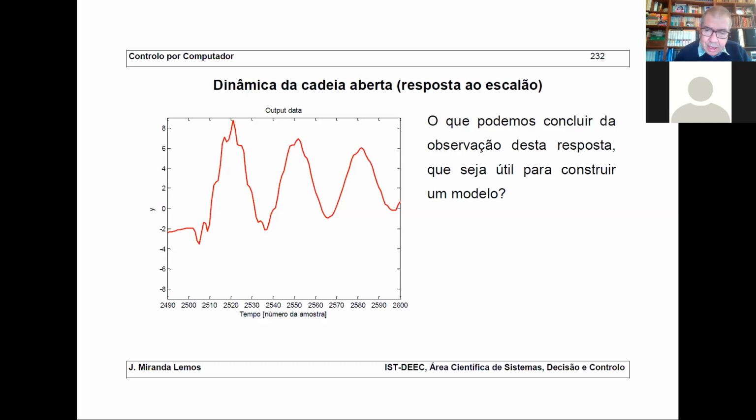This is because the bar works like a spring, and when you rotate it, it does like this, but the initial part turns the other way around. So you have an impulse, I call it a fishing rod effect. So we have a non-minimum phase system.